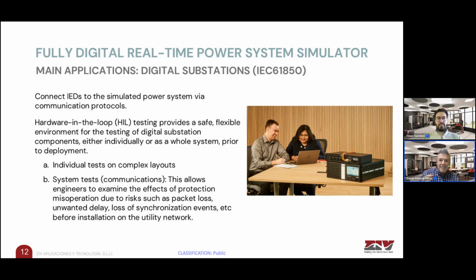So the RTDS simulator gives you also the opportunity to test in your laboratory the behavior of a relay under conditions like loss of packets, loss of information, loss of synchronization, or some delays in the communication. So again, you can see how robust your design is, your relay, under some issues with the communications.